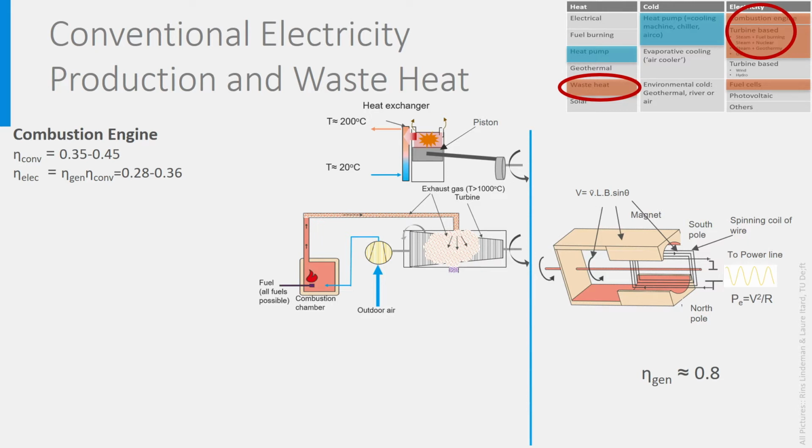The exhaust gases in the turbine are released to the atmosphere, that's the purple pipe below the turbine, with the CO2 and other harmful products they contain, if the fuel is a fossil fuel. Here too, green fuels can be used, like hydrogen. The conversion efficiency depends on the temperature levels, and as more than half of the rotor energy is used by the compressor, only half goes to the generator.